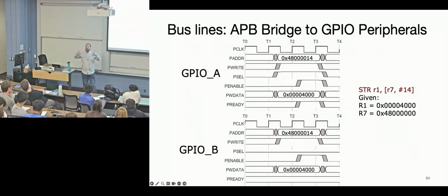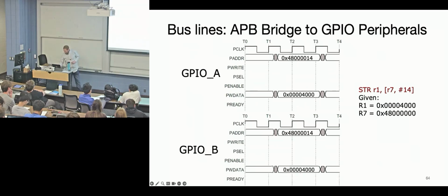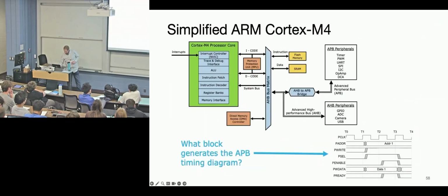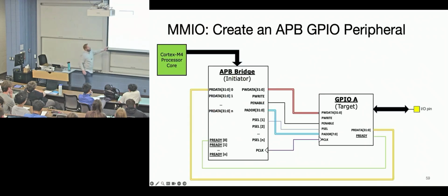Therefore, having those redundant lines on your bus probably doesn't make sense. And so you could imagine there's a state machine here, which says, well, I know there's, say, only 1,000 possible registers, possible addresses, so I'll just reduce that space and I'll reduce the number of address lines.